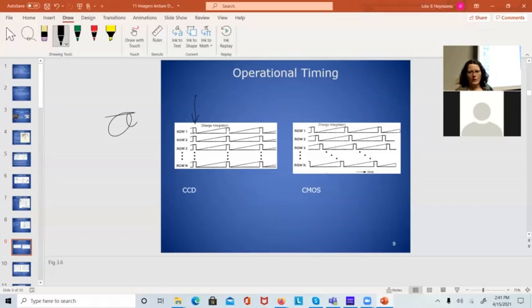And then I'm going to wait whatever my integration time is. And as it's discharged and the voltage changes, then I'm going to read it out again here, and I subtract these two values, and that will be the total amount of signal that I've gotten in that time. I can't really read them all out at the same time, but fairly close to the same time.